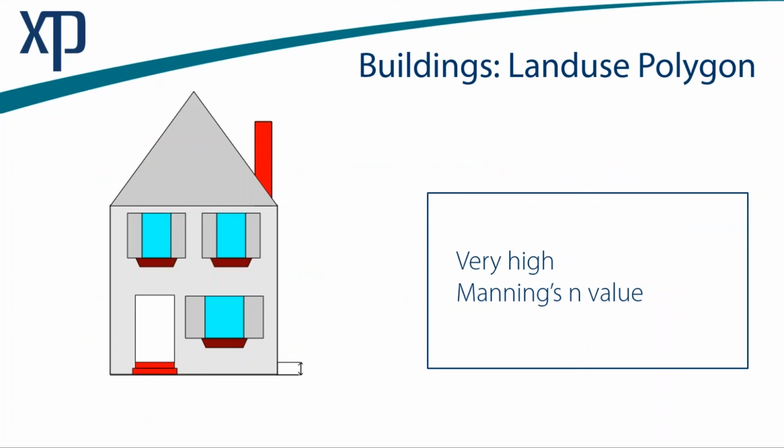So if we use a very high Manning's N value, at some point we might get flow over the building profile. In most cases we're just going to have a shape file with polygons in it. We're going to put an extremely high Manning's roughness on it. At some point water might flow over that representation of a building. There's really not a building there at all. There's no elevation, right?